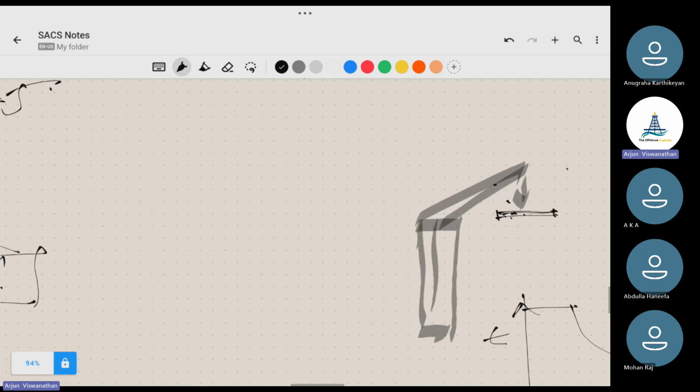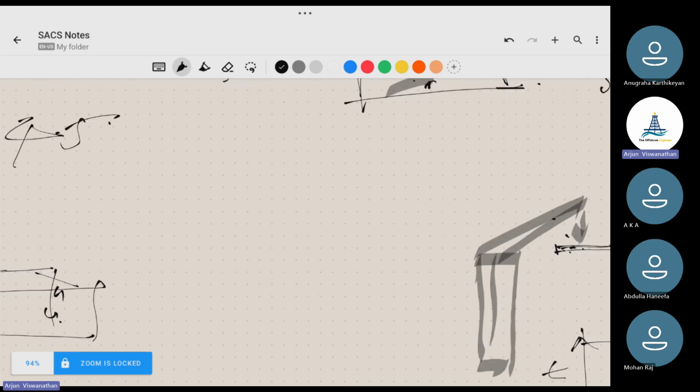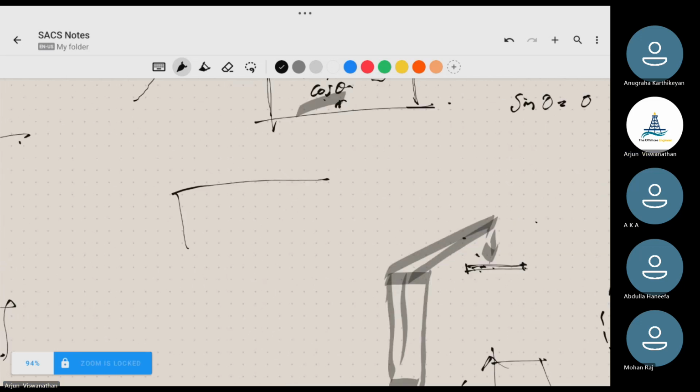While modeling in SACS, there is one more consideration. Usually when we model a sling and the object, it will show some rigid body movement. Because SACS is based on FEA equations, and if a rigid body movement comes, that equation will not get solved.